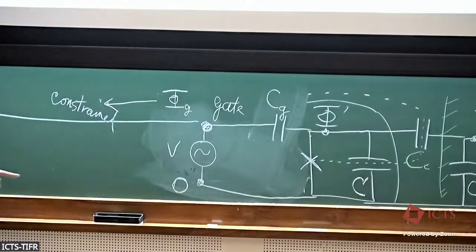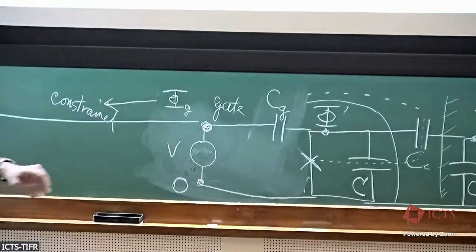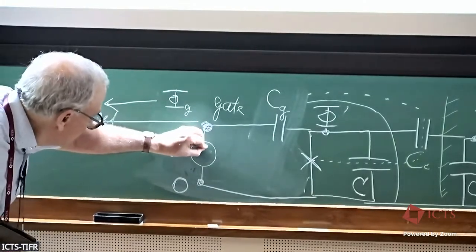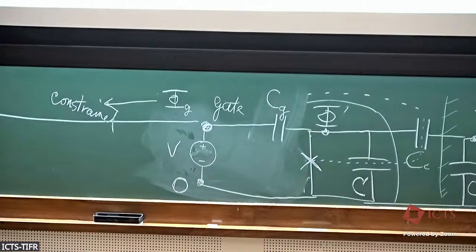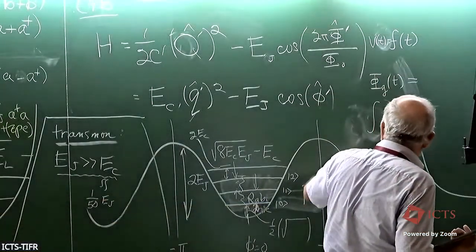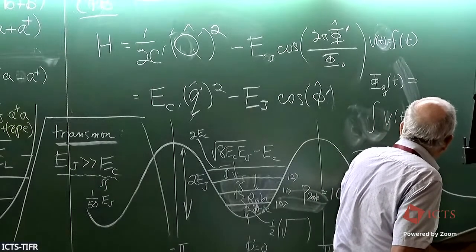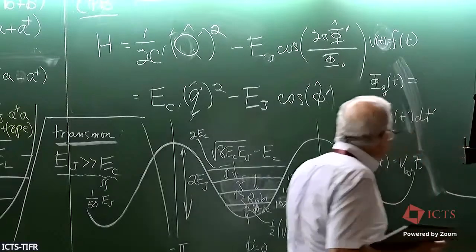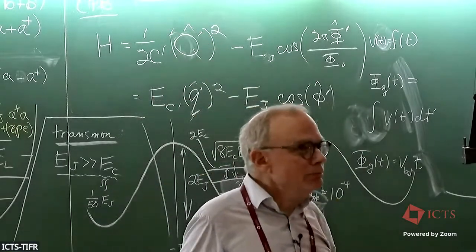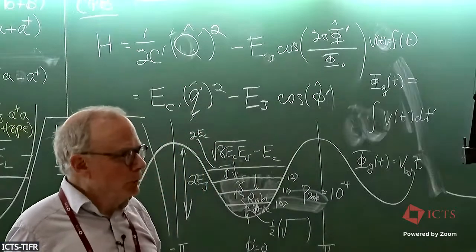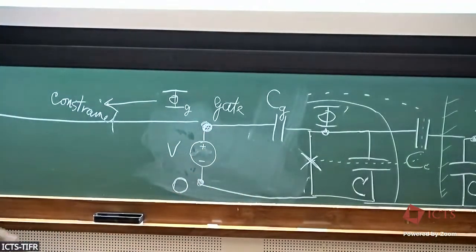Now, so that's how you do drive. Now it turns out, well, another interesting thing you can do that sounds rather more paradoxical is just to put on a DC voltage. Different symbol slightly here, you just say it's a battery. Now, that's a case where F is constant, but then in that case, phi g of t is a linear function of time, V battery times t. Now, that sounds like it's going to give us big trouble. You know, you have this diverging in time value of this phi, and if this were appearing in some expression, if this were an inductor, for example, this would be a really difficult or problematic thing, because now